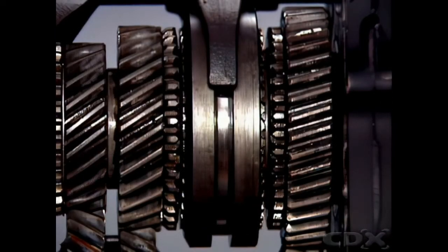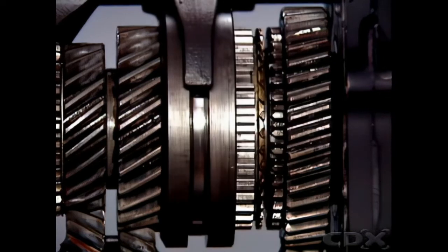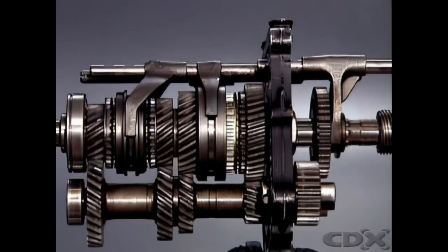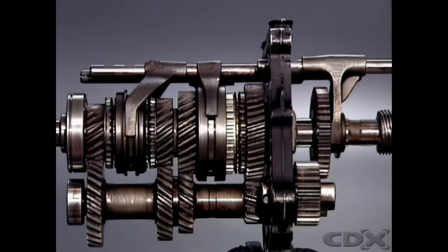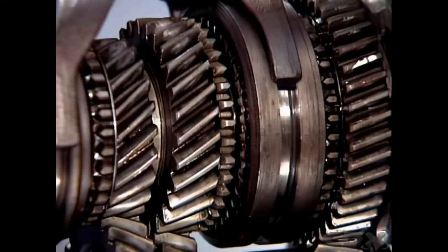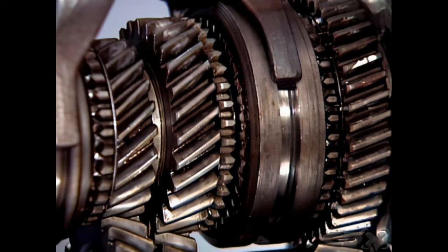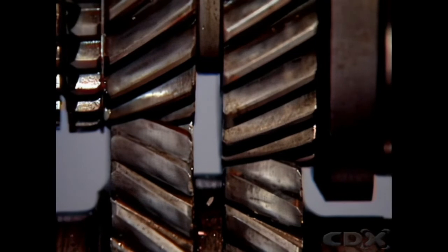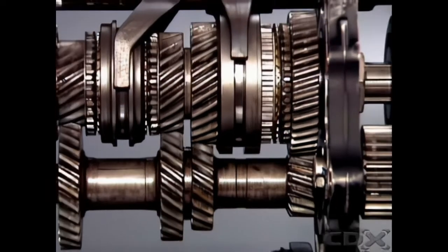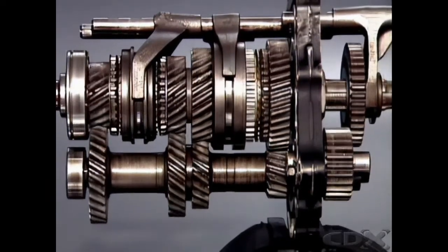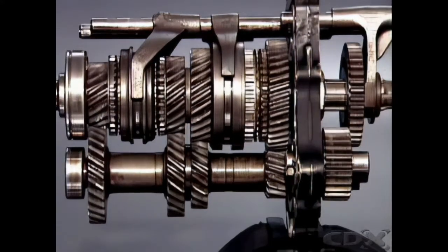The engagement sleeve can slide in either direction to engage the external teeth on the appropriate gear. This locks the gear through the sleeve and hub to the main shaft. Before engagement of the components occurs, a synchromesh device between the sleeve and gear synchronizes them. The gears constantly in mesh have their teeth cut on a helix at an angle to the gear center line. This reduces gear noise and distributes load more evenly, as several teeth are in contact at any one time.